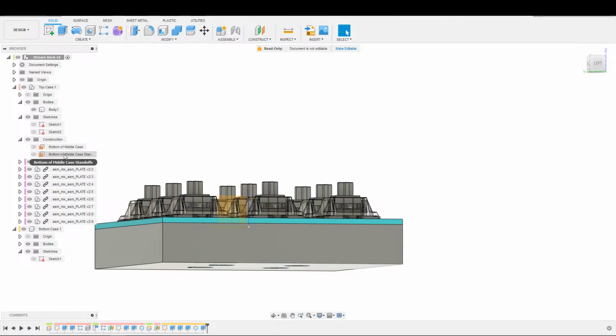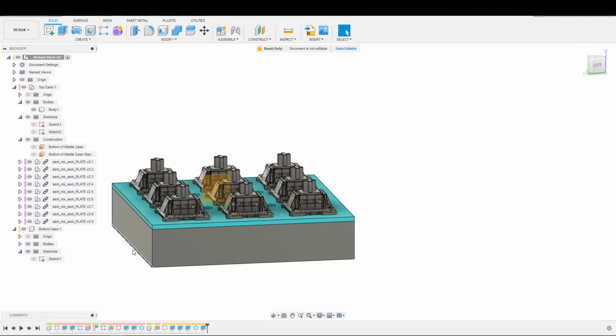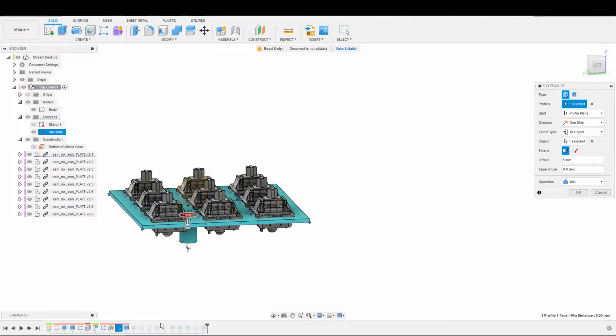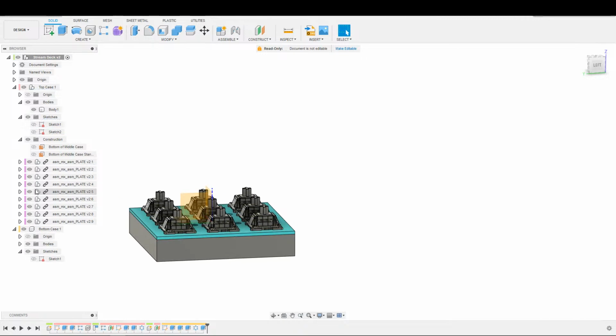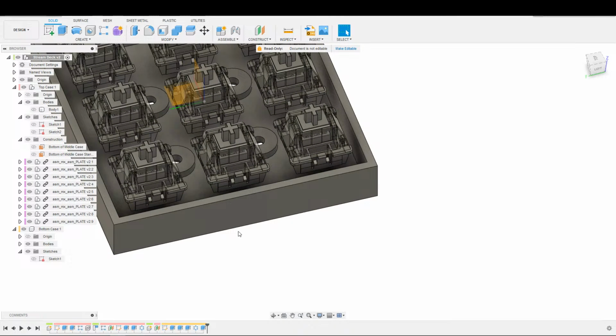The next part we're fixing is this guy right here. I'm going to change it, and do +2. Fine, just 2. +2 is the same thing as 2, but if you're going to be a pain about it. Then I'm going to modify these standoffs to be 2 millimeters shorter, so that's going to be 3 instead, to compensate for the fact that we're coming back up the top. Now I shortened the standoffs so that they're just touching these 2 millimeters that we brought up from the bottom instead of overlapping.